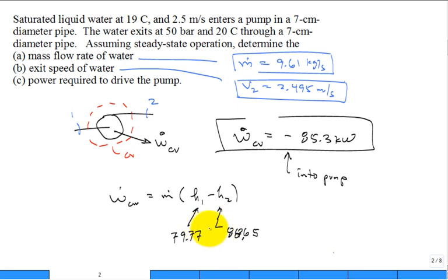We didn't do the kinetic energy because it didn't change? Yeah. The diameter of the pipe is 7 centimeters and 7 centimeters. And what happens is the inlet speed is given to be 2.5 meters per second. Given you can calculate the specific volume in and the specific volume exit, you do find that it's not quite 2.5 on the exit, but it's so close to 2.5 it's negligible. Right, exactly. It would not affect probably the fourth significant digit. That's fifth significant digit in the answer.